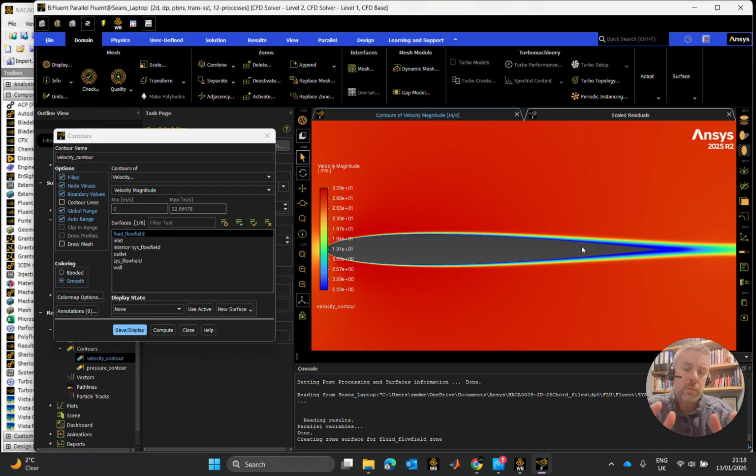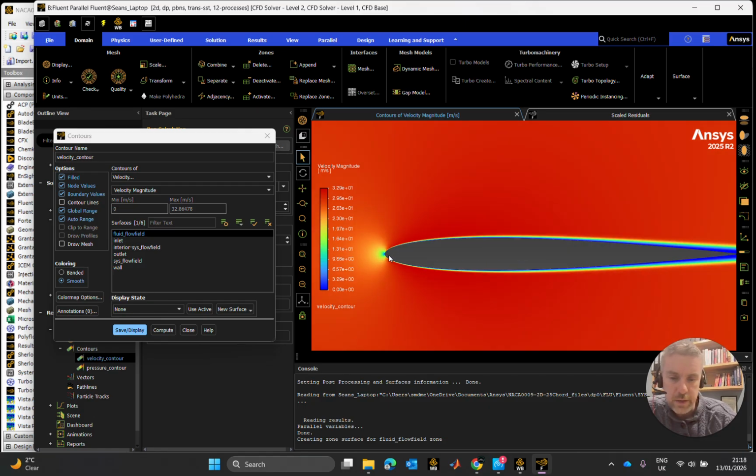And for that reason, we don't want the planform of this airfoil, which I mean the bird's eye view looking down on it, too big. The bigger that is, the more drag you're going to have. Drag is, in our case here, the enemy. So that's one element of the drag, what you can see in this increasing boundary layer.